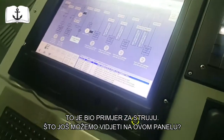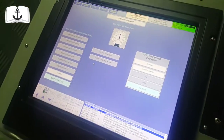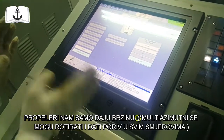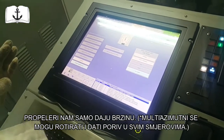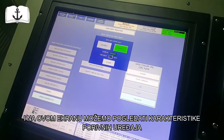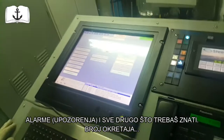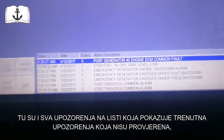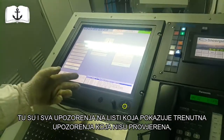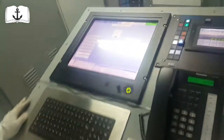What else can you see? We can go to another screen, for example propulsion. We have two bow thrusters, two azimuth thrusters. The bow thruster is not movable, it just changes the speed of the propeller. There you can check the parameters of the machinery, alarms, whatever you need, and see the revolutions. There is an alarm list showing the present alarms that have not been accepted, and you can also go to the log and see the history of alarms. So everything you need is there.